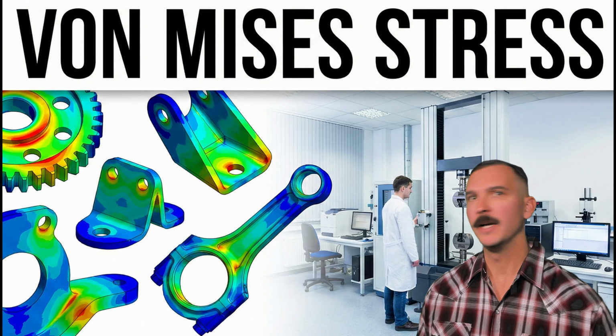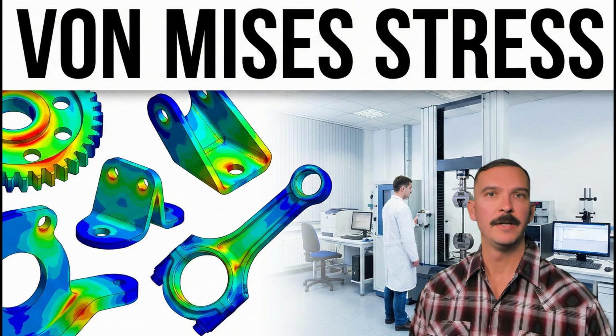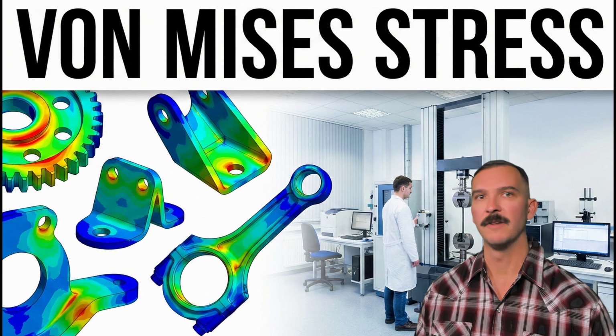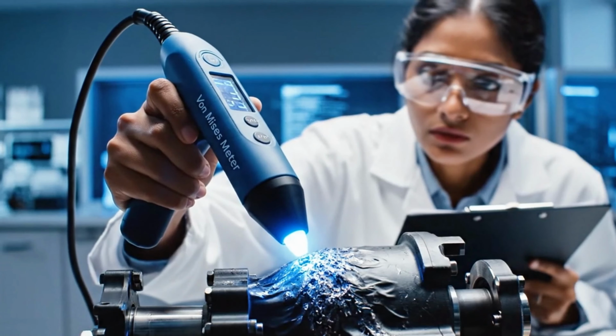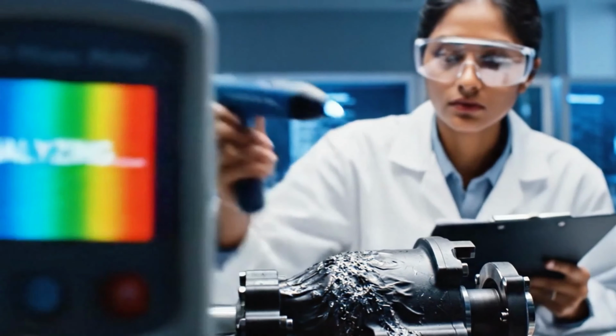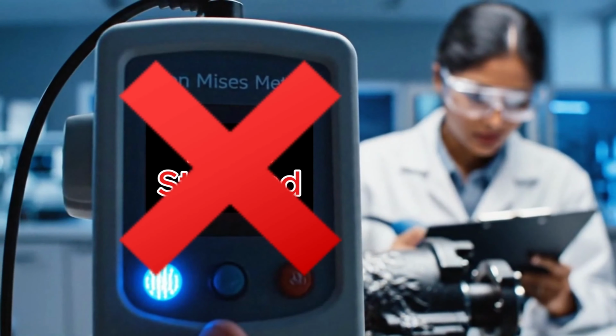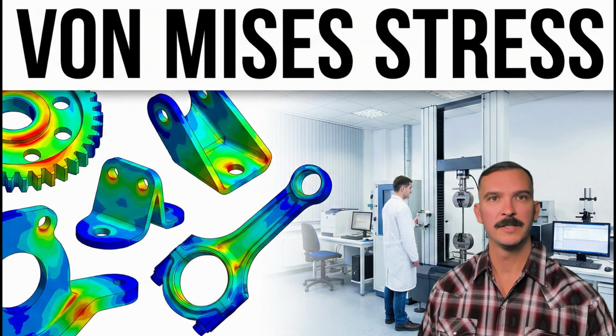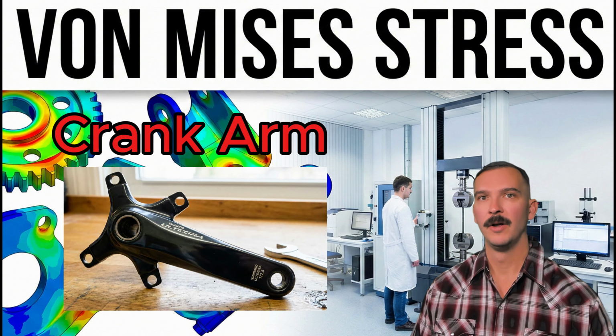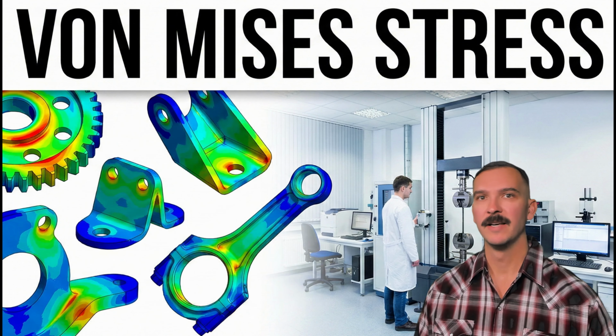If you run a simulation in an FEA tool, the default result is almost always von Mises stress. But you can't measure it. You can't put an instrument on a part and read von Mises. It's a theoretical construct. The problem is that real parts, like this crank arm, are being twisted, bent, and sheared